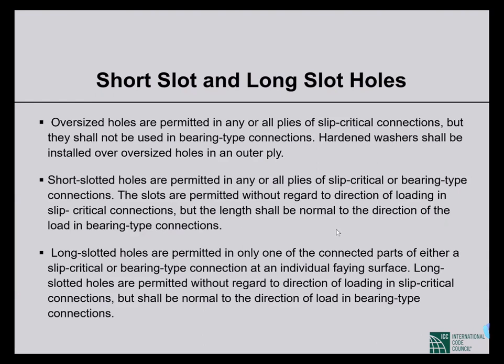Long slotted holes are permitted in only one of the connected parts of either a slip critical or a bearing type connection at an individual faying surface. That is, there will be holes on both the plates, but in only one plate can we have long slotted holes. We cannot have long slotted holes on both the plates.